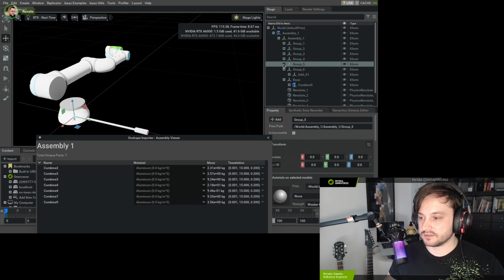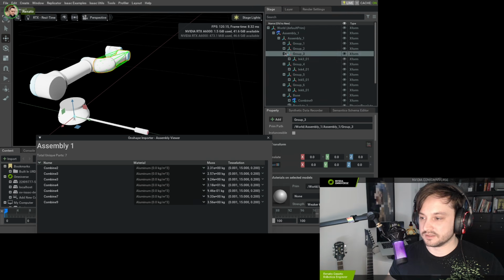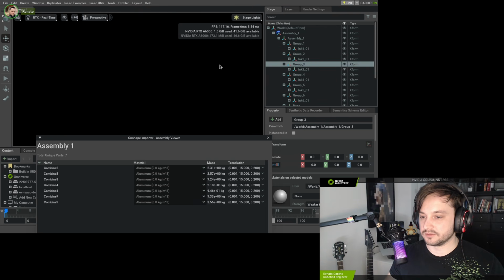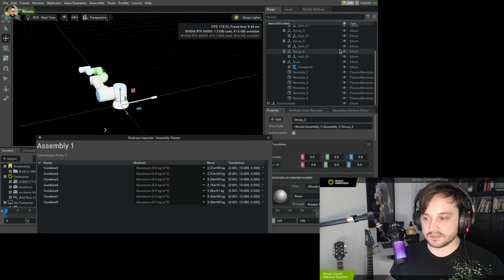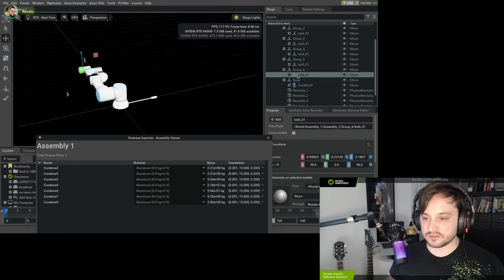Same thing for others. Oh, and because it is all in groups, now things are kind of hidden away in the groups. Let's undo that. But before doing that, let's just double check. Okay, origins are in the right place now because it did move everything together. So let's undo all these groups here. I just deleted the groups on Onshape.